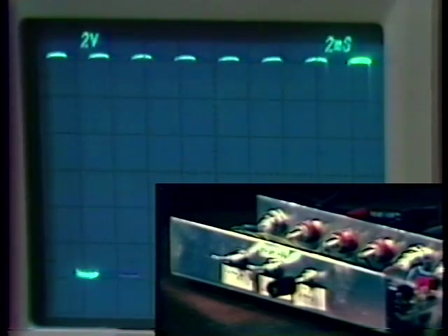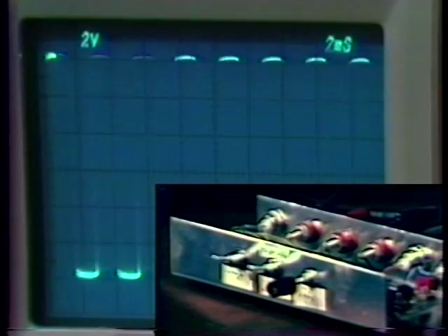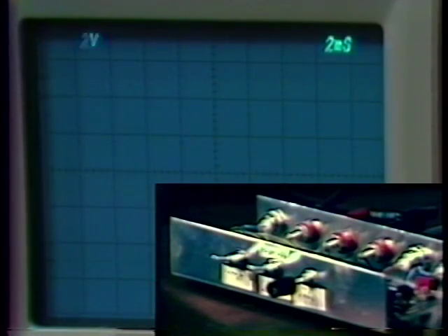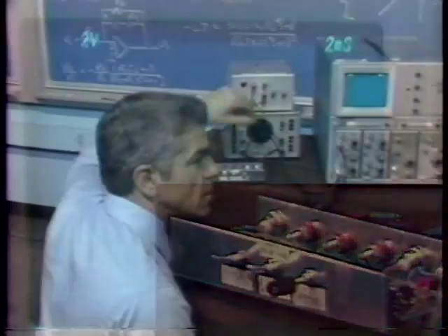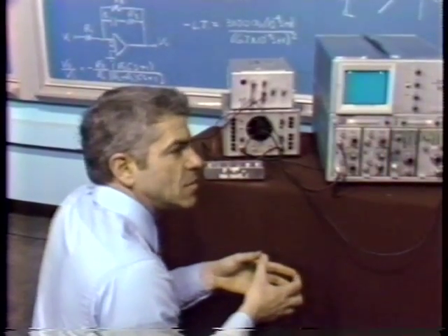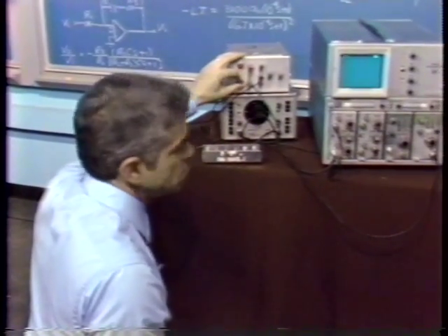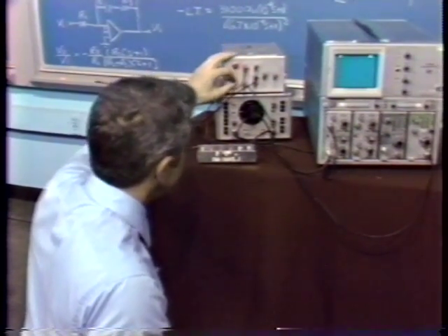Whoops, we lost. This is really a flip the coin kind of situation, because it's entirely possible that during the startup transient, we somehow kick the system, get into the large amplitude case, and the system oscillates. That time we won. I turned on the power supply, turned it off, turned it on again. Turns out this time, just by flipping the coin a second time, the system started in the stable mode. We now have the large value for A0, an A0 of about 80.